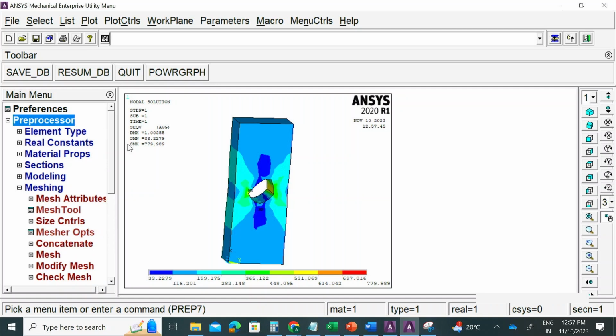We are at least going to do like 6-7 meshes, and then we will have some conclusions, and there is no bar to it. You can keep on doing 10 or 15 meshes. The thumb rule here is we have to eventually go beyond 10,000 elements. That is the sweet spot. Typically your results tend to converge well after 10,000 elements. Sometimes it doesn't converge till 20,000 for very complex models. So we'll find out.